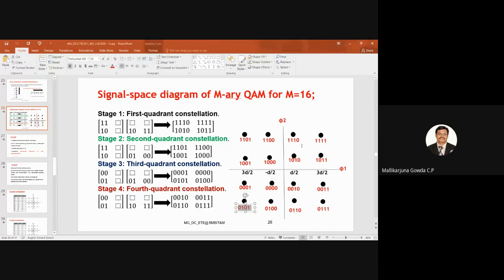Outer square and inner square. Two things I said. So there will be one bit change since it is a gray encoded bit. So this is your outer square. You just check with the adjacent code words. There will be one bit change. Again, even from here to here also. So 0 to 0 is there. Next, 1 to 0 is the change. Then two ones are there, two ones are there. Okay. Yes, got this idea.